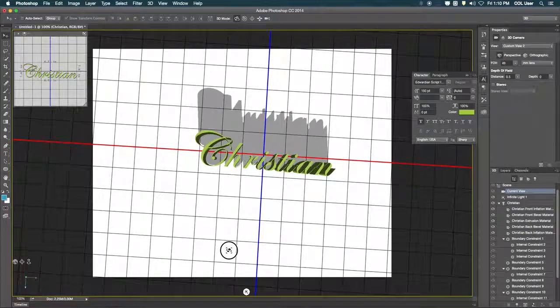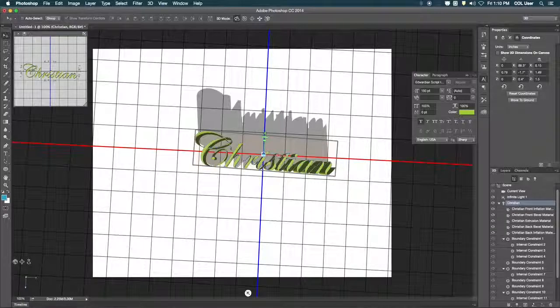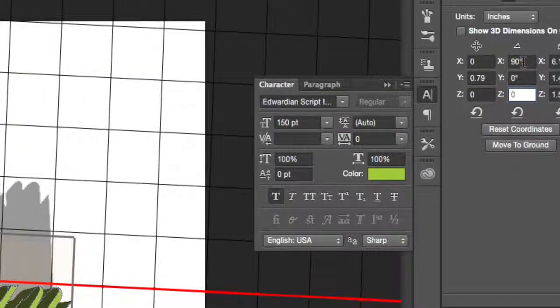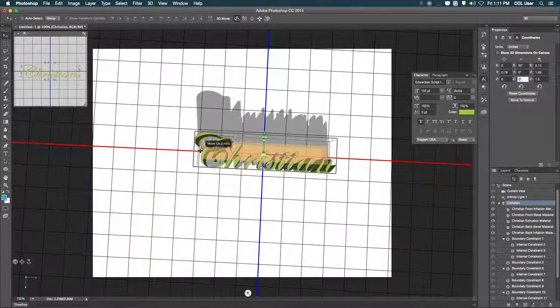So you can see there's my name. Let me just make sure that this is on the ground completely. I'm going to change that to 90, and 0, and 0 to straighten that up. So what I did over here was I put the x angle directly at 90 degrees, I put the y-axis at 0 and the z angle at 0 as well, just to straighten out my name on the line to make it look a little bit better for the printing process.